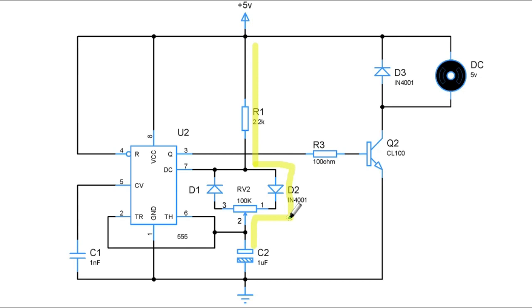So if you know about a variable resistor, it has 3 different terminals, and when you modify the pot, that is the center cylindrical thing in a variable resistor, you can observe there will be a different resistance exhibited. For example, if you modify the resistance value using the pot, you can observe different resistance between 1 and 2 and 2 and 3. That is what we are trying to achieve here. So let's say you have modified this resistance value, which means this charging current will experience different resistance here than the discharging current.